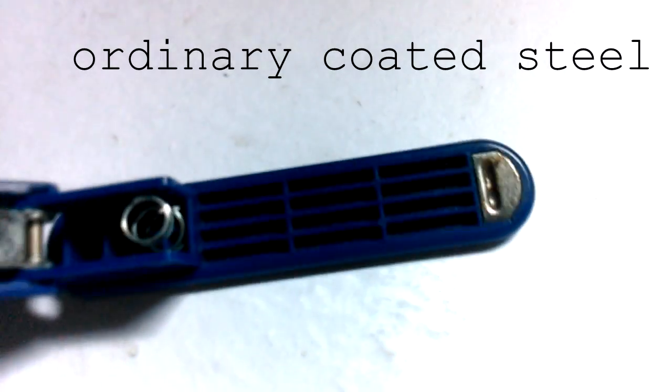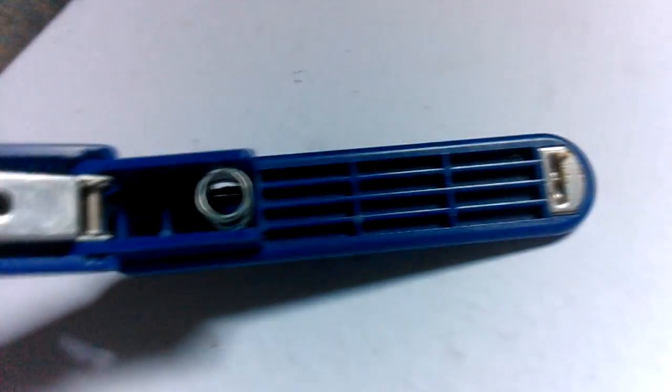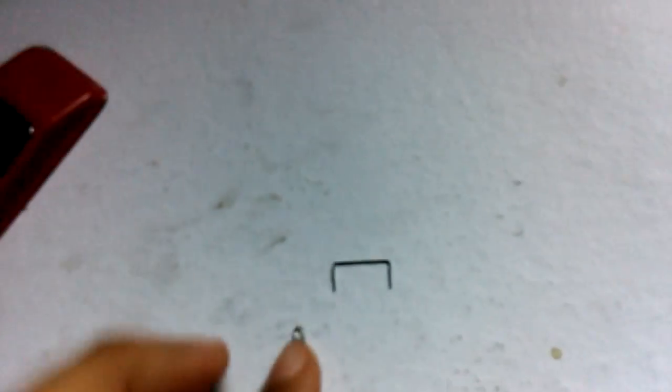In our model, it is made of ordinary coated steel, and through time, you can observe that there is rust that has accumulated already in the crimp area. The crimp area is the area where the staples make contact and deform their legs in the anvil. One of the possible reasons why rust developed in this area, considering that it is coated, is due to how